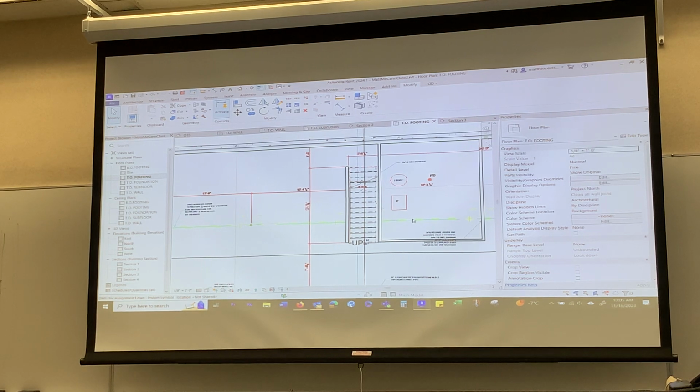Oh, your stairs aren't high enough. Are you in a section view? You cut your section in the wrong place, so you don't get the handles. The handles are only going to appear at that midway point, so you need to move your section back or something. Nobody wants edit boundaries, not getting the handles. Okay, we can do that. It's just that edit boundary, or edit stairs, and then the handles will come and I can just drag them to match. Don't drag the handles, the arrows, yeah.